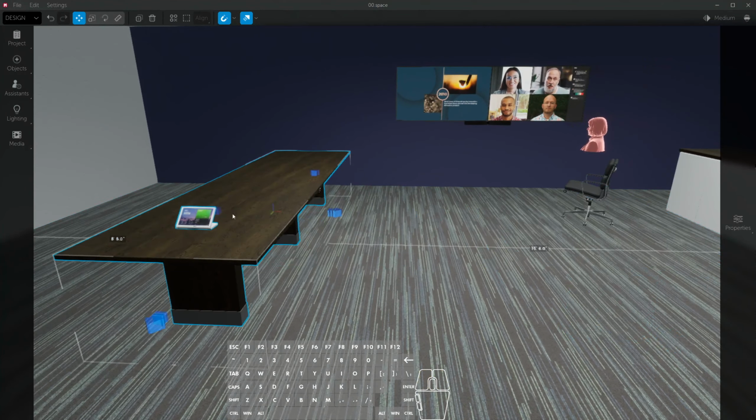All right. Before I do anything else, I'm going to grab our divisible wall so we can make sure that it is exactly halfway across. To do that, I'm going to make sure I've got my snapping turned on. I turned this off previously in a project because I was having some problems getting these to stick to the floor and not into the middle of the wall. But let's go ahead. Still in the architecture tab, or I could just look for operable wall. That is the name of our divisible wall object.